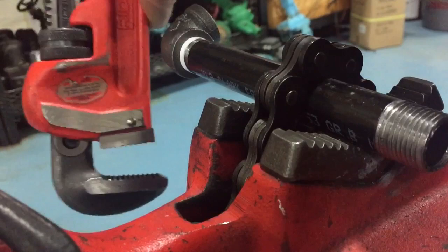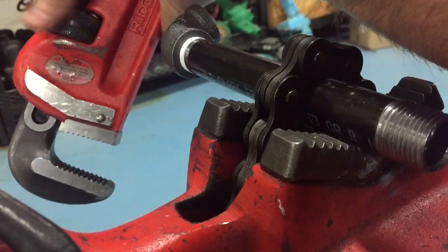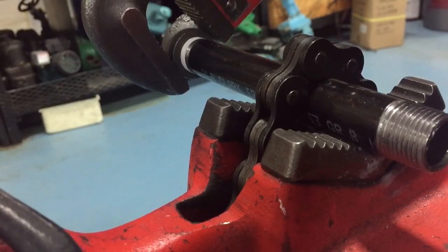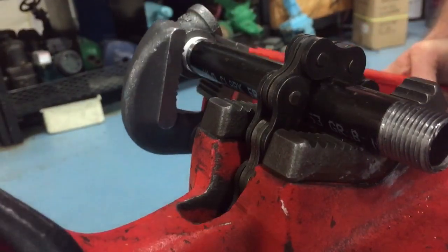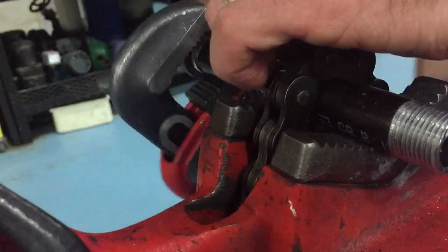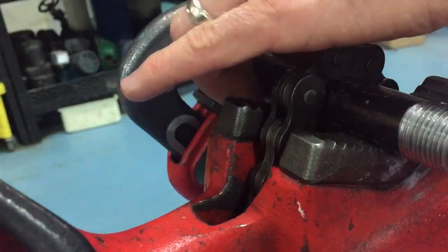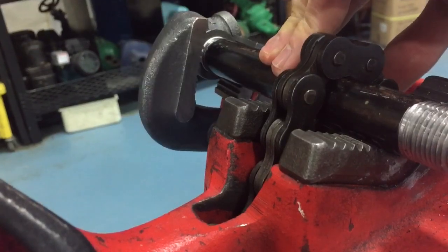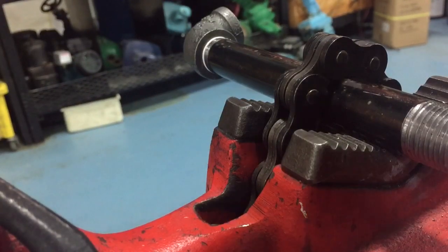But you can see here on the pipe wrench it can be resized, right? So we want to make sure it's sized appropriately for our fitting. So that's about right. And we want to turn this clockwise. And we should be able to turn it 2 or 3 times here. Go to about there, and we'll just have a look to see how many threads we have left.